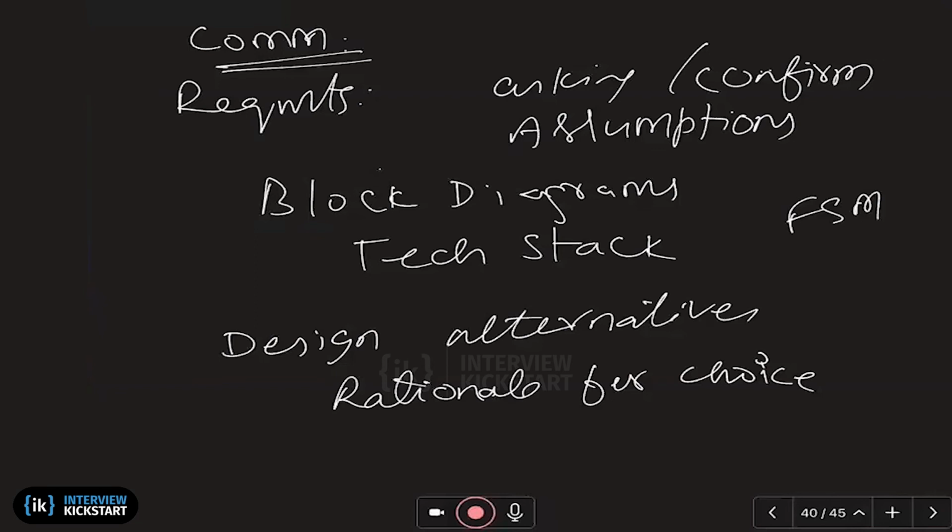Obviously you won't choose a multi-core processor platform for a thermostat. Those kinds of common sense filtering you can do, right? As an embedded engineer, you should know which platforms and microcontrollers are popular for which applications. It's a professional upkeep that you have to do, scanning magazines or whatever, to know the applications. You can read the processor application notes. The semiconductor vendors publish all kinds of information about the various applications.